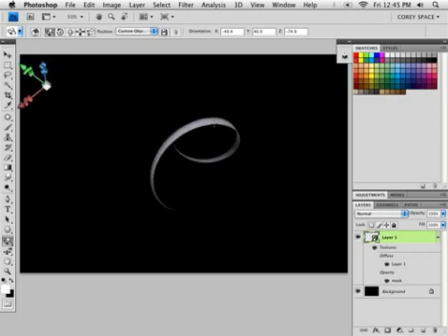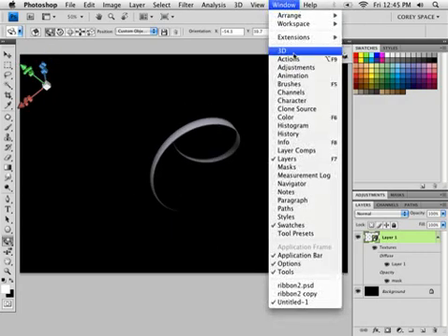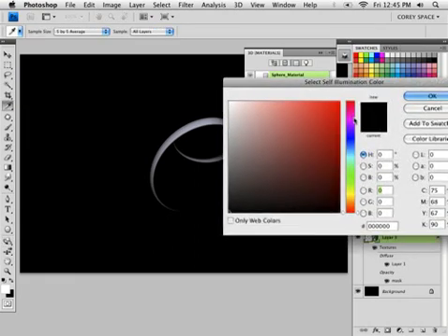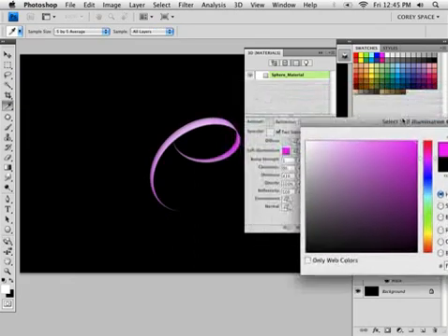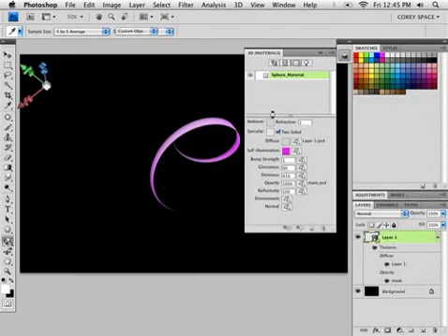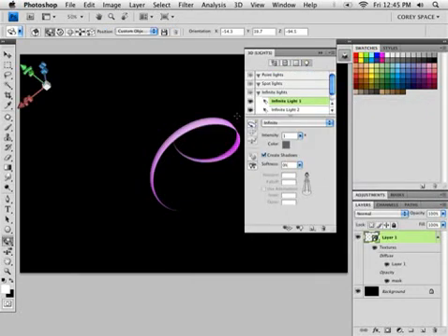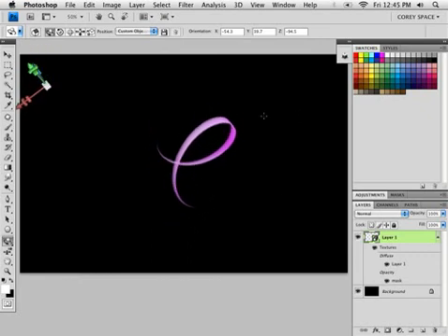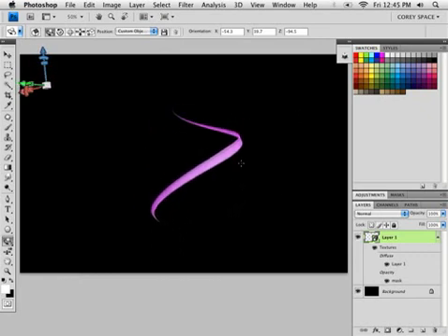But I want to change the color. So let's reopen that 3D panel, and in that same material section, you've got a section here called self-illumination. If you click on that and simply choose a new color, the object will assume that color there, as you see. And it's using the lighting that's inside this scene. You see we've got some infinite lights here. I'm going to leave those alone. And now I can maneuver this around, and I've got a fully colored object.